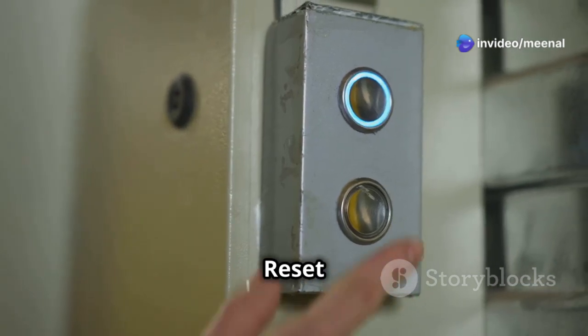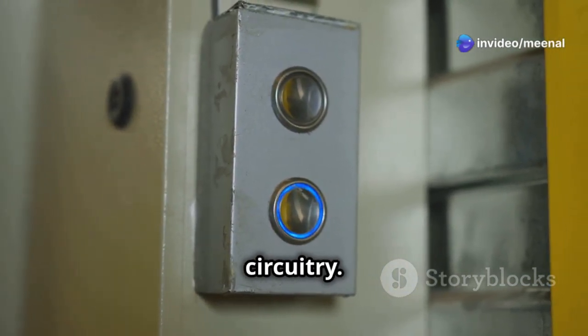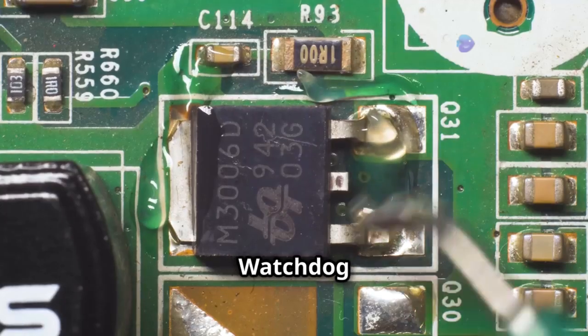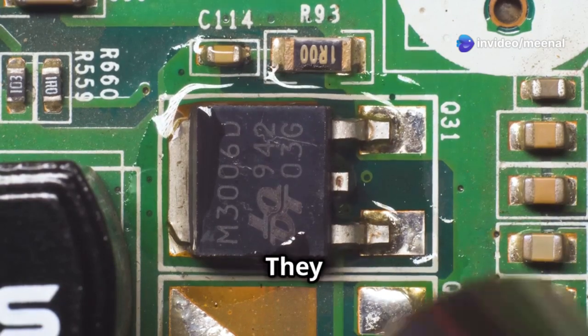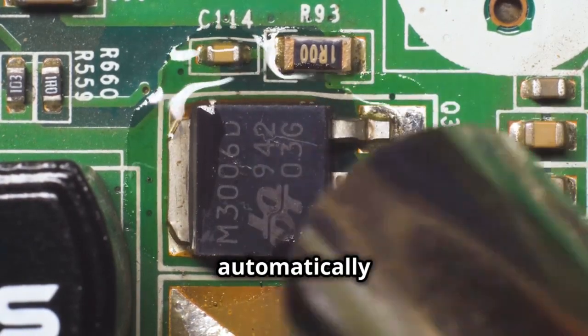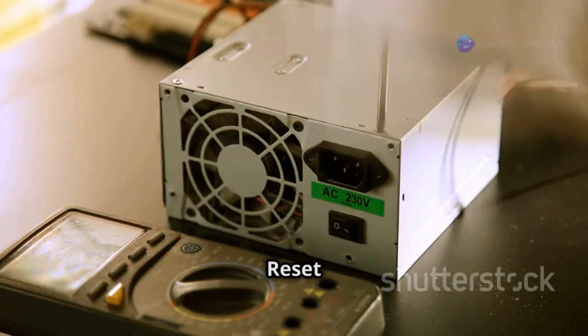Push-button reset ICs work with manual reset switches and include debouncing circuitry. This debouncing is essential to prevent multiple resets from a single press, ensuring a clean and reliable reset signal. Watchdog timer reset ICs monitor the system for malfunctions and generate a reset signal if needed. They are critical in applications where continuous operation is vital, as they can automatically reset the system if it becomes unresponsive.